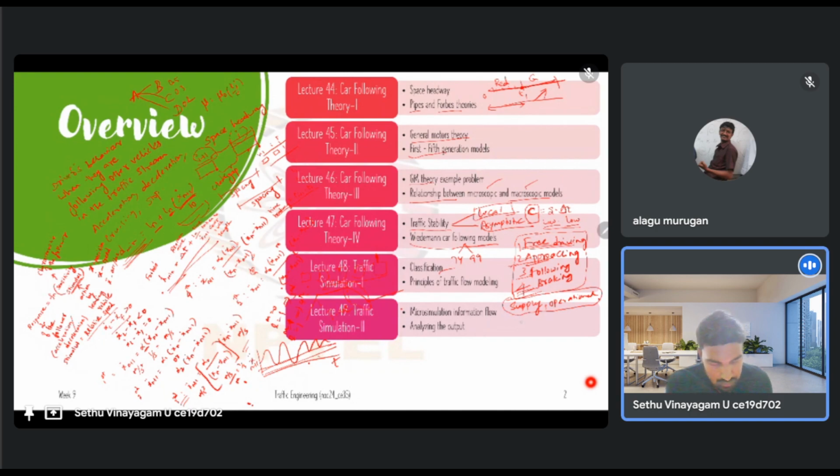The other aspect is the demand aspect. This is how many vehicles or how many people want to use the system. This can be supplied in terms of an OD matrix, from one zone to another zone, how many people want to travel. Again, this OD matrix can be static or dynamic. Static means that at any time of the day the demand is going to remain the same. Dynamic means that for different times, a different number of people will want to move between the different traffic zones.